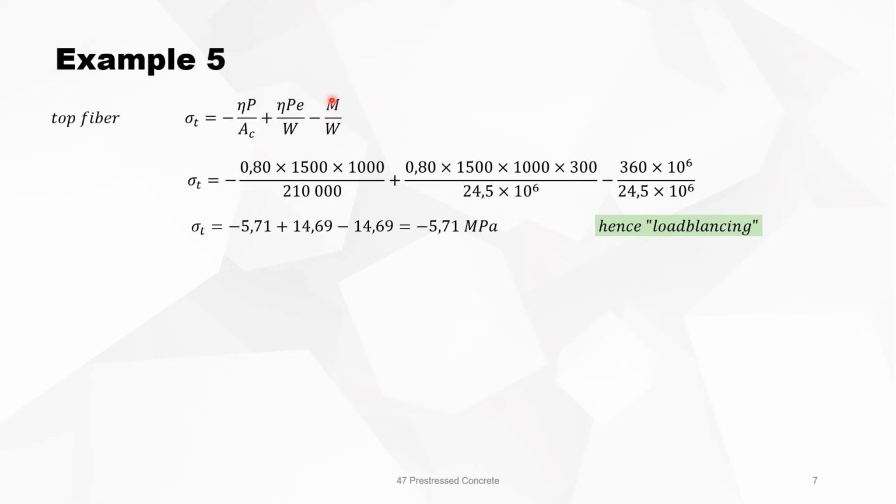So the bending moment caused by the load on the beam equals the P times e, equals unity. So that's why we call it load balancing. You put the pre-stressing force in it in such a way that the load on the beam can be taken.